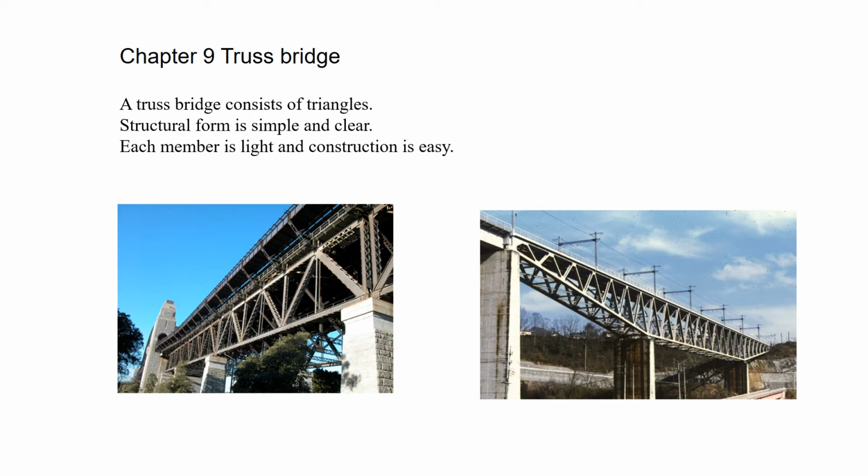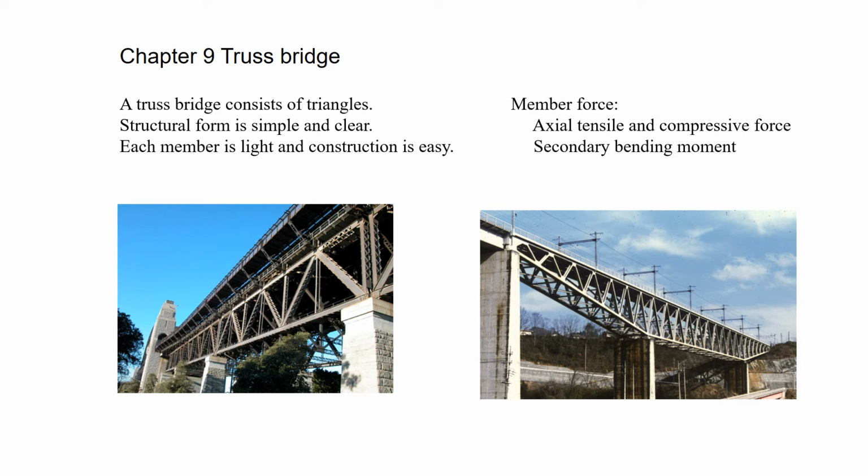Its structural form is simple and clear. Each member is light and construction is easy. The member force is axial, tensile, and compressive force. At the connection of members, secondary bending moment occurs.